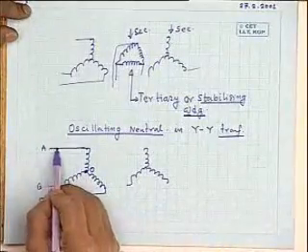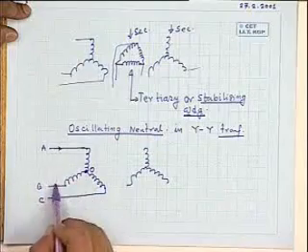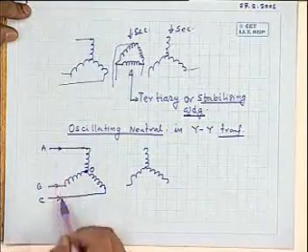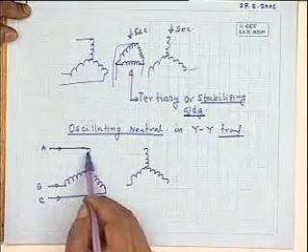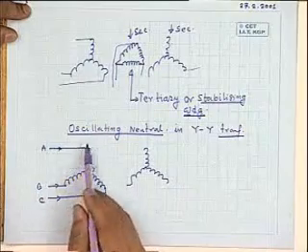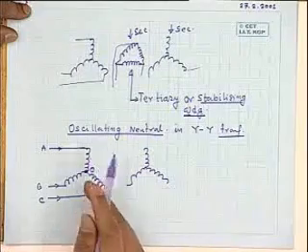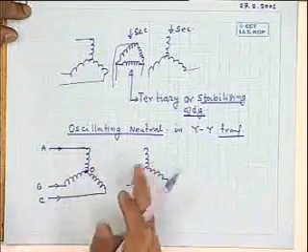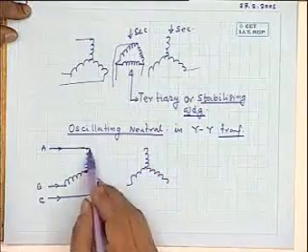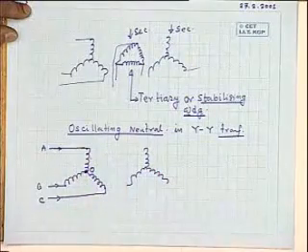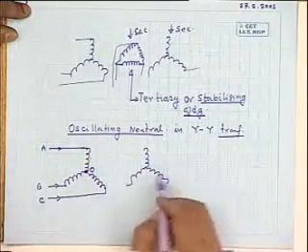Now, as told earlier, since the magnetizing current here will have only a fundamental component, the flux in the core will contain a third harmonic component, and the induced voltage in each of the windings will contain a fundamental and a third harmonic. In each winding, fundamental and third harmonic.